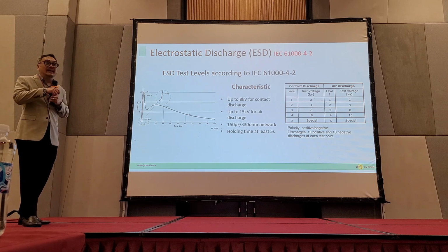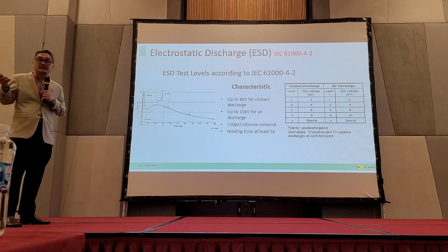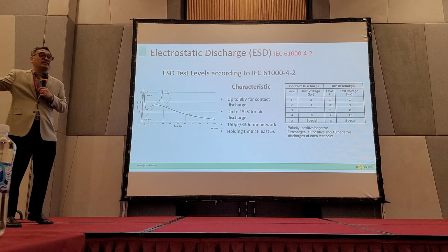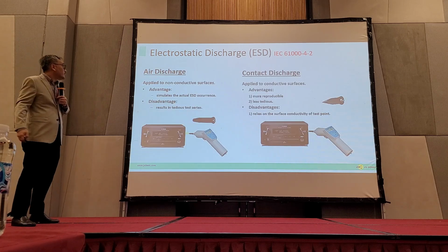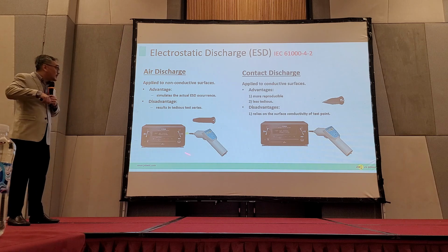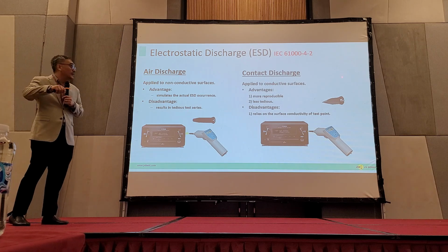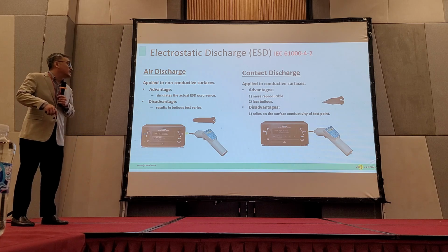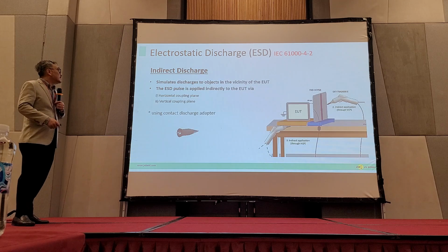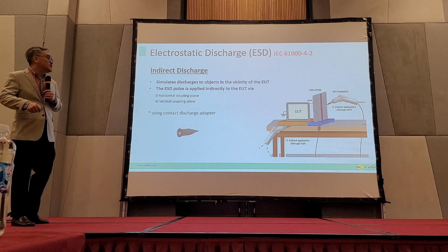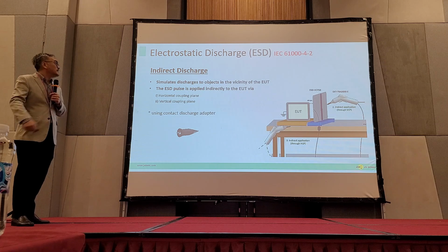So we have a demo of this ESD generator outside. If you are interested, you can have a look. And we have an expert from EMC partner as well for the ESD. So different kinds of tests: we have air discharge and we have contact discharge, and they test on a different area. Then we have indirect discharge, and we test on a different area as well.